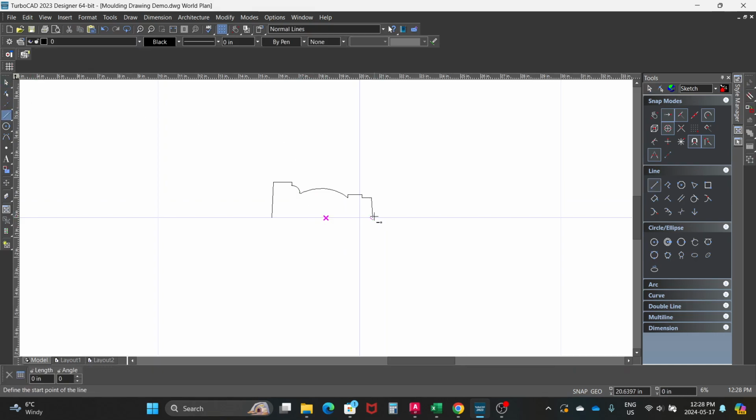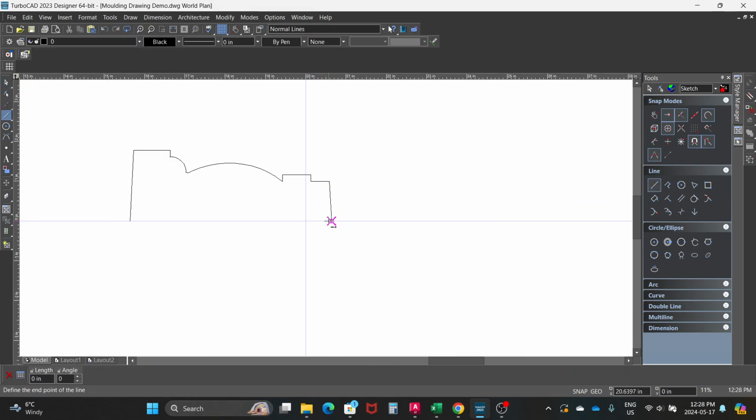And to draw a template, basically, I'm going to scroll back over the node or the place where I started the line to get the construction lines, and I'm going to tab over till it's highlighted in the lower left hand corner there, and it says length.